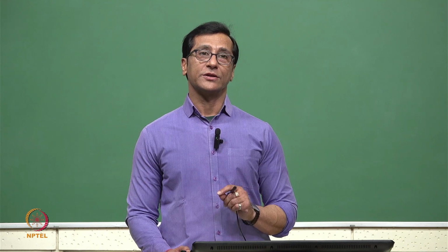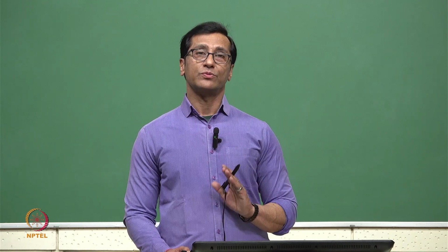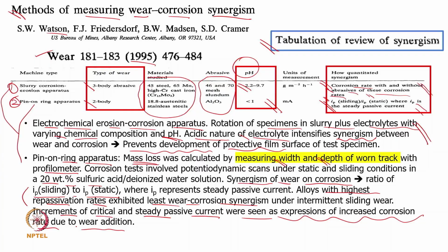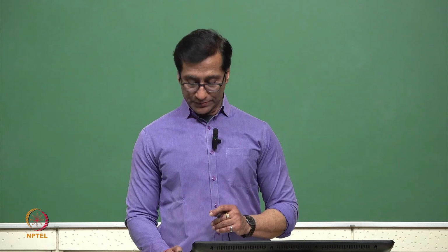However, with a material which can repassivate immediately, this synergy can be reduced. So if we are able to provide an electrolyte at pH 7, it may have lesser problems, or maybe on a basic side, maybe 8 or 7.5, it will give very good results. Coming to the passivation side, a material which can passivate immediately will be preferable.